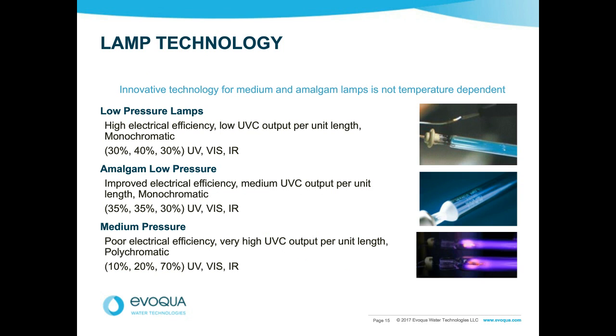Look, if we go back to what's out there now, look at the existing lamp technology. The oldest lamps are 30% efficient. Some of the modern amalgam lamps are over 40% efficient. Now, the modern amalgam lamps are up to 1,000 watts in output. The most powerful LED used for UV is only about 5 watts, and these lamps are only about 1 to 1.5% efficient. So they currently are only really suited for very, very small flows.